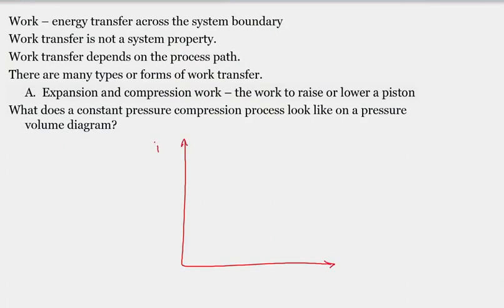the PV diagram. And again, we said that work in its most general form could be expressed as an integral moving from one state condition to a second state condition. So that's S1 to S2. And the most general form of that expression is one where we use just some force times the distance that force is executed in that process. So from state 1 to state 2, force integrated over that distance, over that process distance.